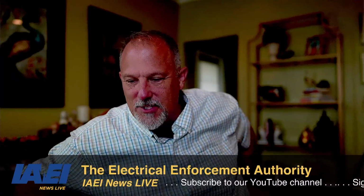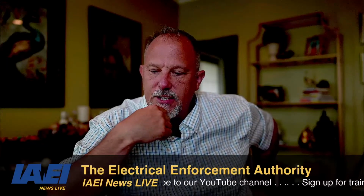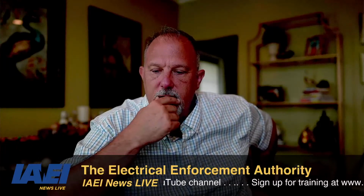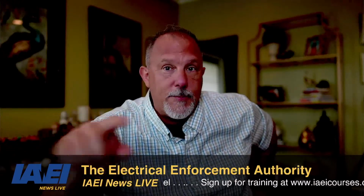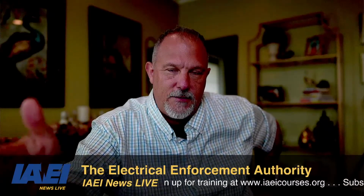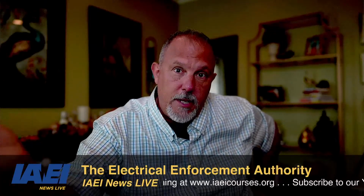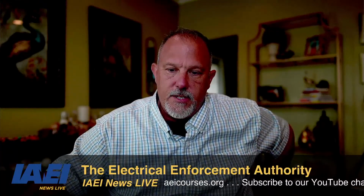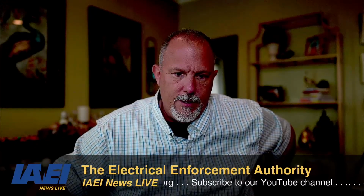Caught and confirmed. So Don Gannier, a misapplied breaker, one in a circuit that has more available fault current than its interrupting current, would no longer be an OCPD? No, that would be a misapplication. You're right, Don, you're absolutely right. It would become a bomb. It's no longer an overcurrent protective device because you're applying it outside of its rating. It will explode probably and give you a big boom and all that jazz. It becomes something that is, what's the term? Ungood.